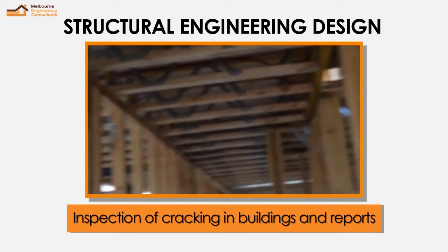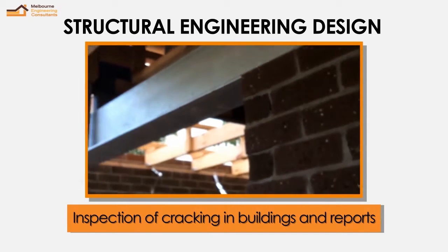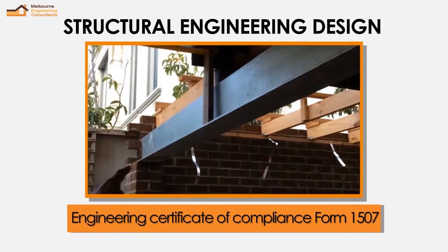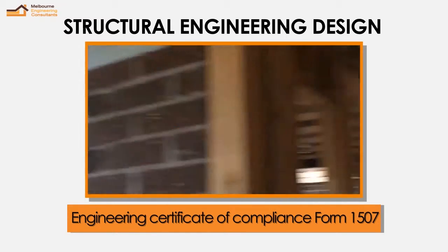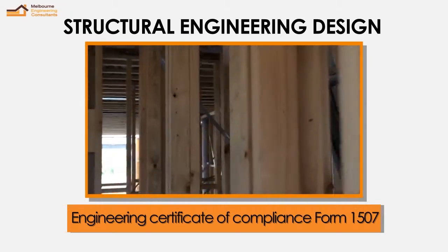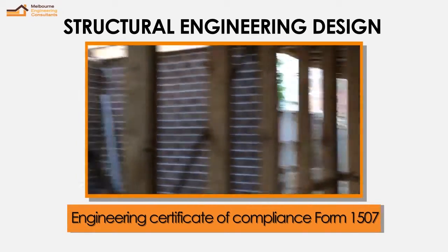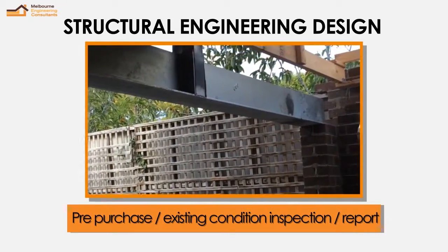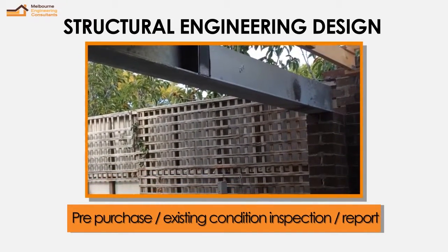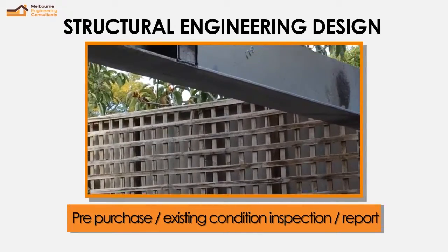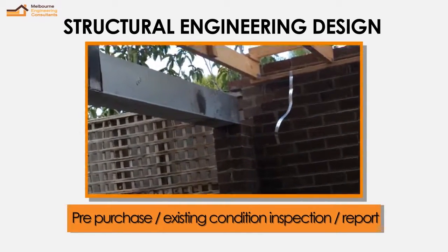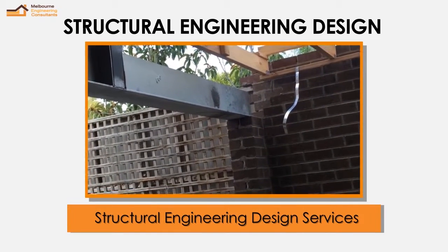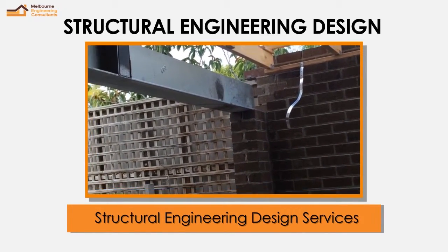Here this one is the garage beam, it's a T section, and it's picking my first floor steel beam with a stub column which I'll show you on the other side. So that's again a garage lintel beam, and I'm taking the point load from the steel beam which is picking my first floor walls and the roof, and the load is transferred through that steel stub column and onto the garage lintel which is a T section.